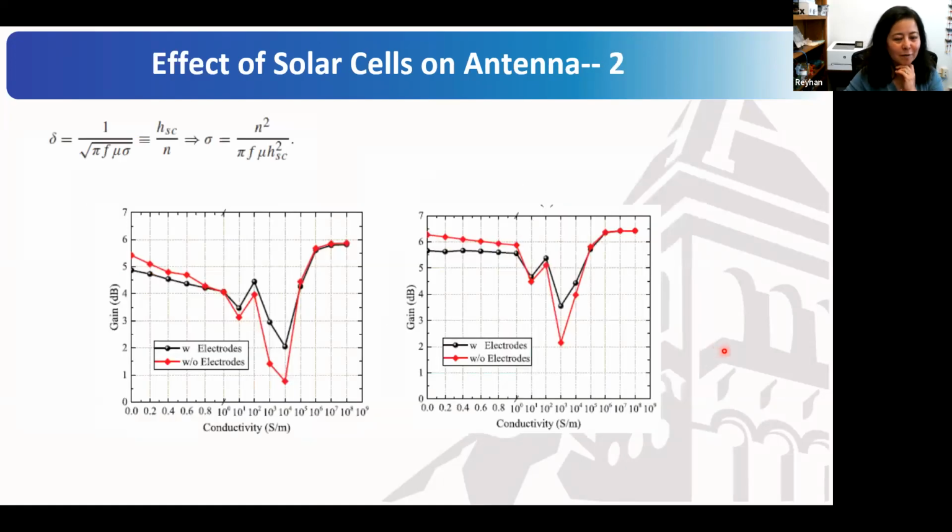At first look, it's kind of disheartening a little bit, okay? What it says is, right now, let's say we don't know exactly how conductive the germanium and the doped germanium layer is. So let's say we're just gonna vary its conductivity to see how it affects the gain. If it's not conductive, fine, it is just a substrate. If it's conductive, like a copper, fine, it's just to raise the ground. So these two will not affect our gain.